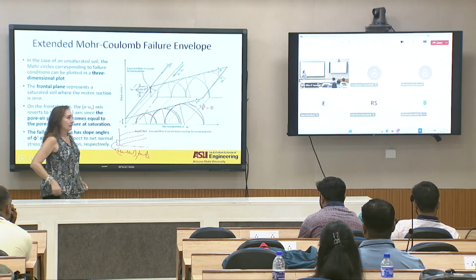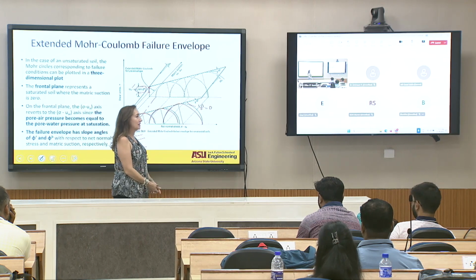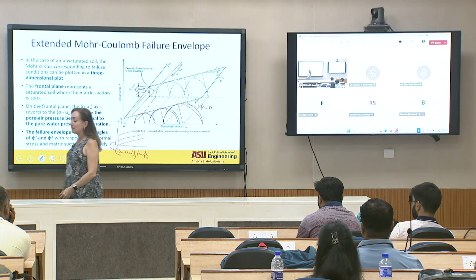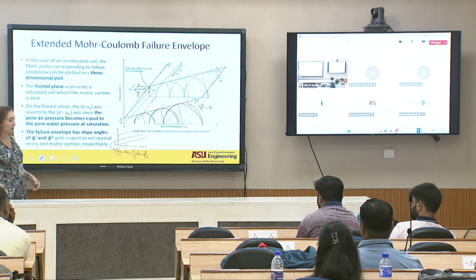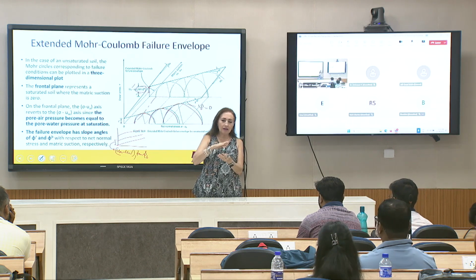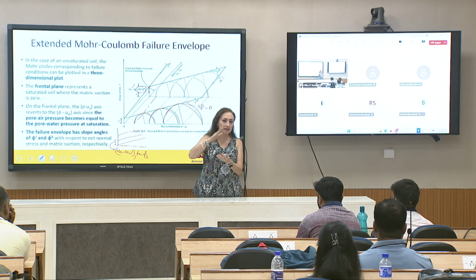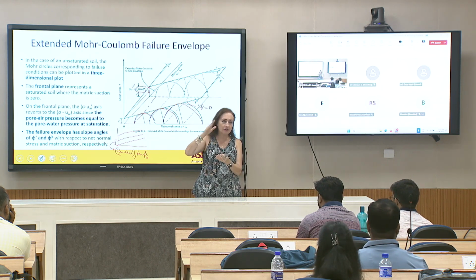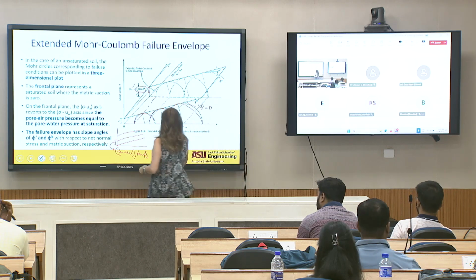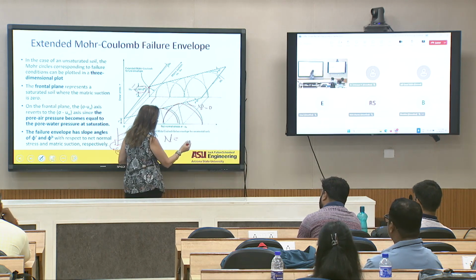There are more theories that relate to that one, but in pavement analysis and design there is a different model. They don't use Mohr-Coulomb models. When you have a lot of repetitions, as a function of your deviator stress, the deformation keeps increasing until it fails.